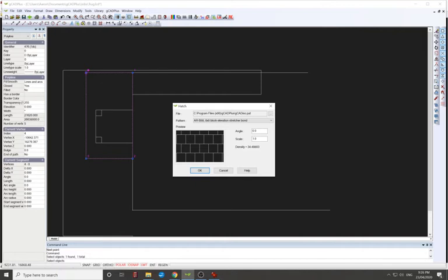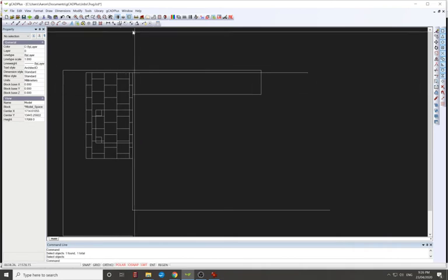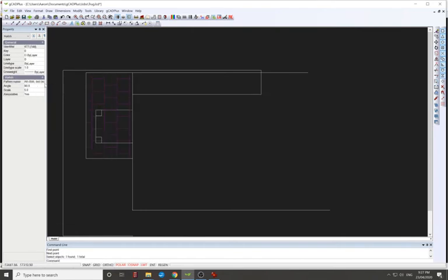I'm not sure what it will look like. I'm going to turn it around 90 degrees, and I think, let's just say 5 for scale and see if that works. Okay, they're too big. So sometimes, say I want to do a 400 by 400 tile, I might just go to tool and go distance and see what that's coming up as. That's a 1000 tile, so we're going to go half that, so 2.5. You just click on the hatch, scale, clear that, 2.5, enter, and then we've got our paving there.